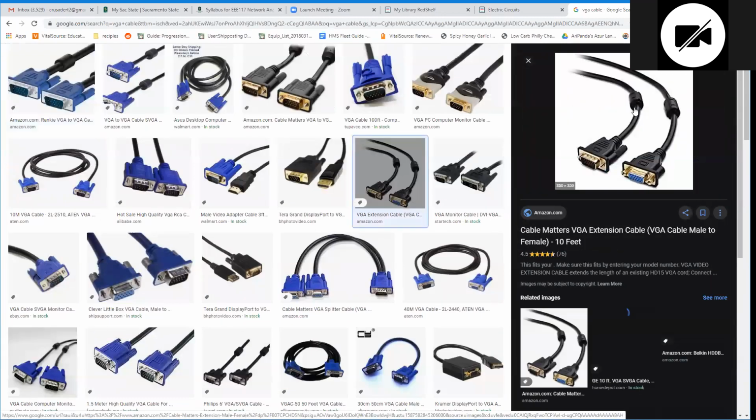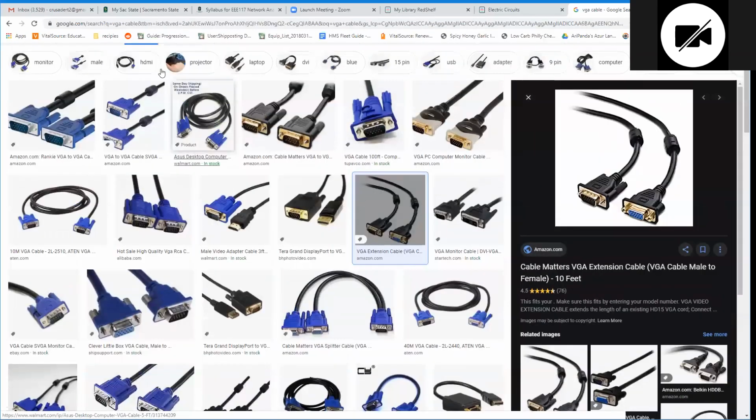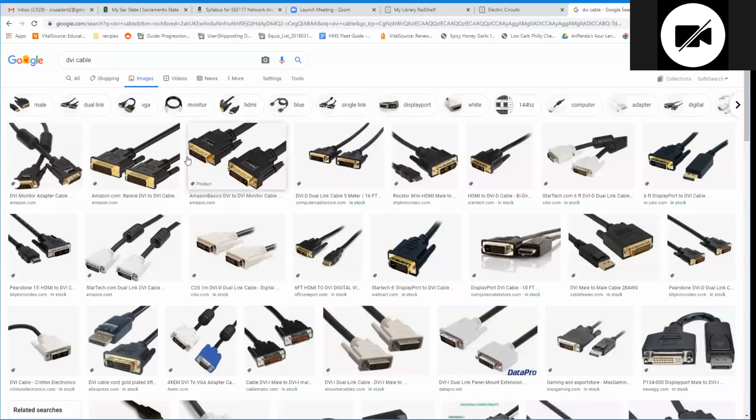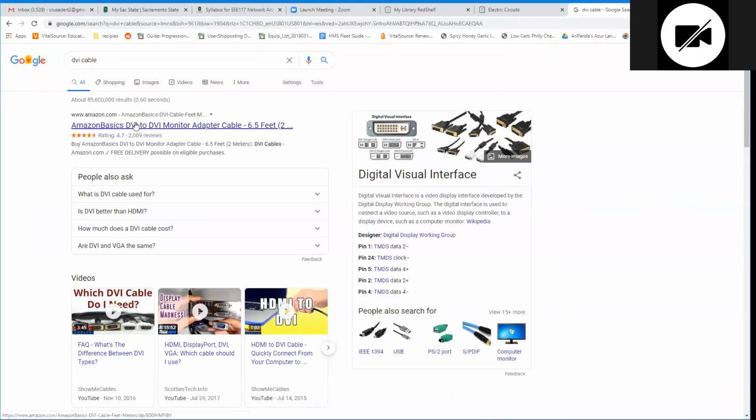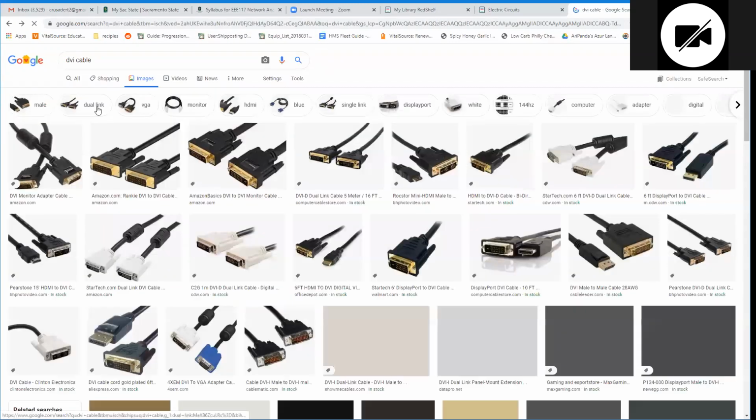These things are, again, filters. I don't think DVI has them, because some of them do, some of them don't. Once you get to DVI and HDMI and all that, it's a digital signal. A digital signal doesn't really need that. It's old school analog signals that really needed them, because analog signals can be really messed up by noise. When you go down to digitalized signals, we have a lot of error checking algorithms that we can use to rebuild a waveform otherwise, but old school analog didn't have that, okay?